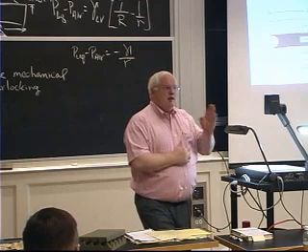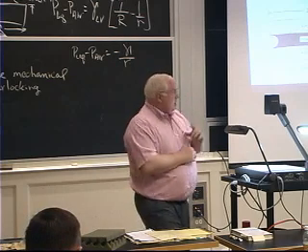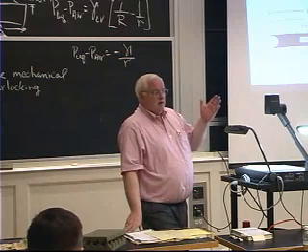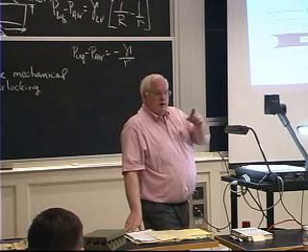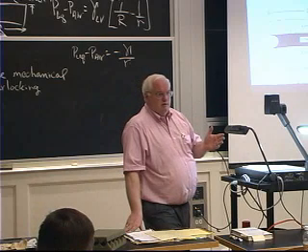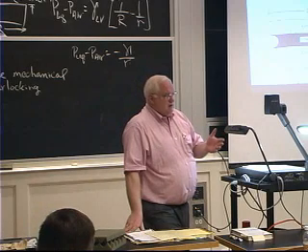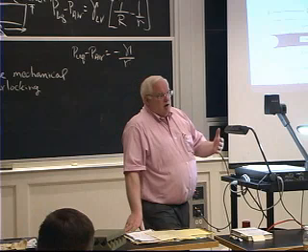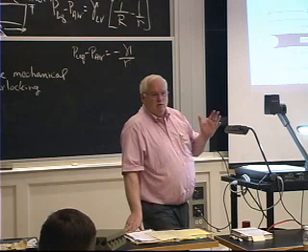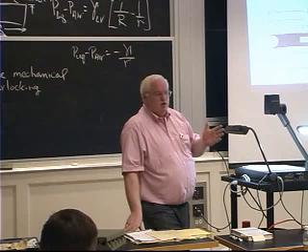Holding something to 1/10,000th is 1 part in 10,000. Holding it to 50 millionths over 1 inch is 1 part in 20,000. Holding it to 3 inches on one of those blocks is 1 part in 60,000. And it's pretty impressive. And now you're talking about a 1 or 2 degree temperature change will essentially wipe out your precision.